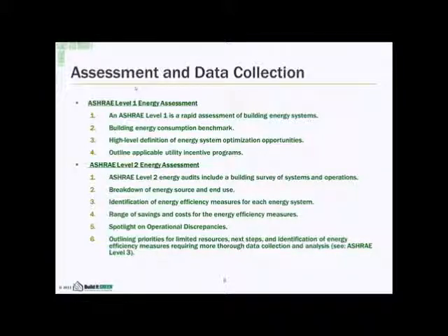The type of assessment data you're going to be collecting and receiving from your assessor is pretty much an ASHRAE Level 2 assessment, and that is built off an ASHRAE Level 1 assessment. ASHRAE Level 1 is just a really general high-level overview of the building. The ASHRAE Level 2 is more of a survey, and gets more into the systems and operations. It breaks down different end uses, and it identifies measures or what's wrong with the building shell or systems, HVAC systems or domestic hot water systems.